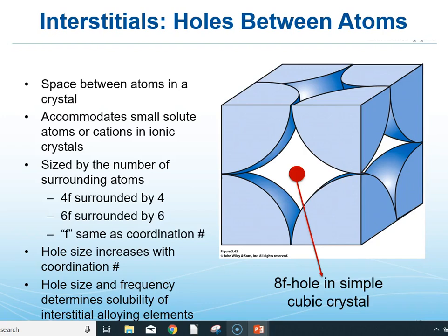And these are very regular spaces. So there's a periodic array of the holes, or the largest spacing points between the atoms, just like there's a regular spacing of the atoms themselves. So periodic is periodic. An interstitial is literally defined as the space between atoms in the crystal. If you have an ionic crystal, your cations, given that they're much smaller in atomic radius than the anions, will sit in these interstitial positions, and that will effectively form an interlocked lattice, the cation positions themselves.